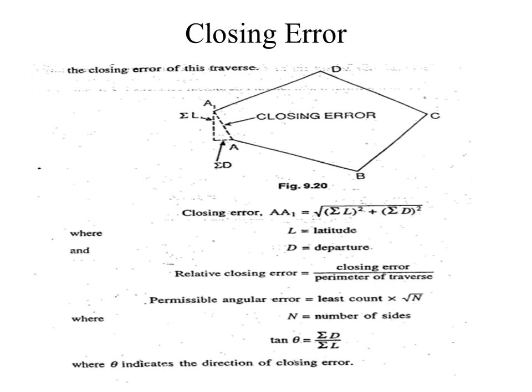Again, vernier A is set at 0 and upper clamp is kept fixed. The lower clamp is loosened and the ranging rod at E is bisected. Now the clamp is tightened and the upper one is opened. By turning the telescope clockwise, the ranging rod at B is bisected. The readings on the vernier are noted and the angle A is obtained.